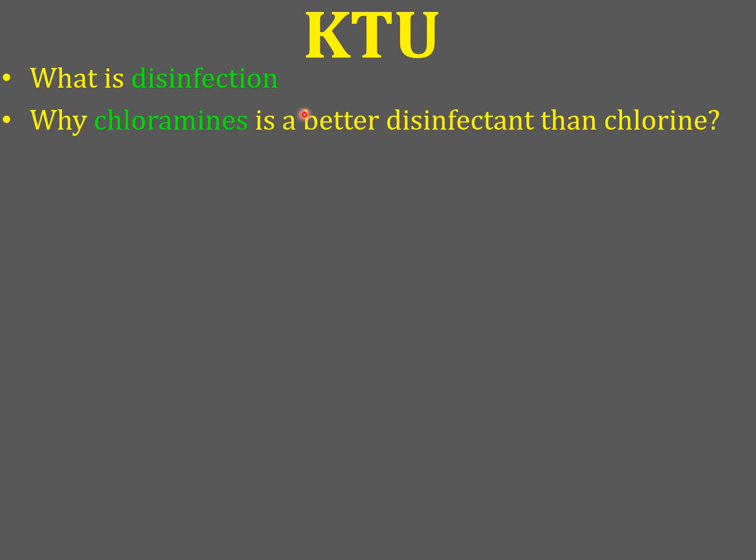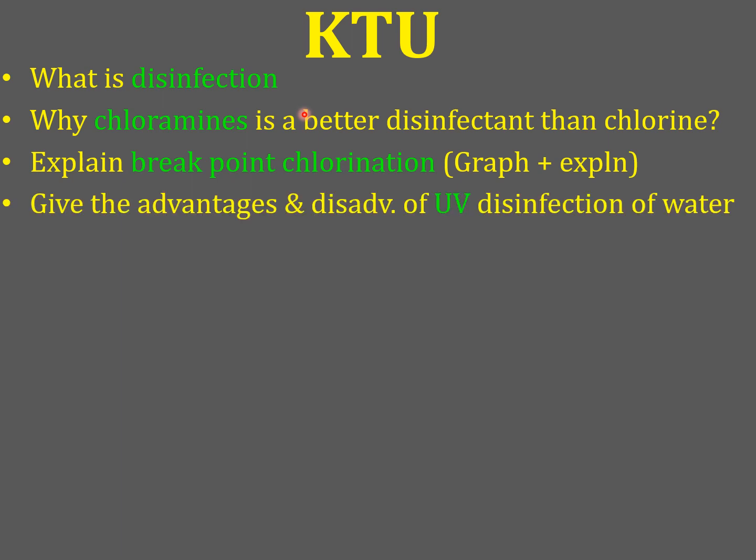Here we are coming to the end of the session. As usual, I am here with a few K2 questions. What is disinfection? Why is chloramine a better disinfectant than chlorine? Explain breakpoint chlorination and the advantages and disadvantages of UV disinfection.